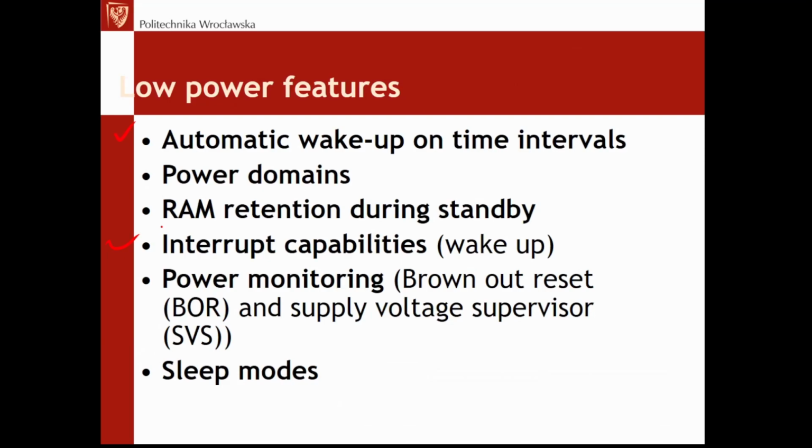The microcontrollers without these features usually are woken up only through the reset, by setting a reset line low or active. Yet this is really limited, and it means that only the old processors have these limited capabilities. All new processors for use in low power circuitry allow waking up on some intervals or wake up timers.